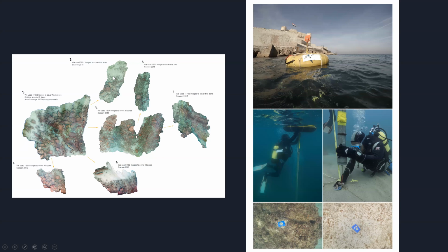The reason we take an overlapping area is to make sure that the georeference has the lowest error possible, because, like I mentioned, when the French mission made the GIS data in the 1990s, there was a big error in the X, Y and Z location, between 50 centimeters and 1 meter and above. But the final error for the location of the site itself is less than 10 centimeters, which is a totally big difference.